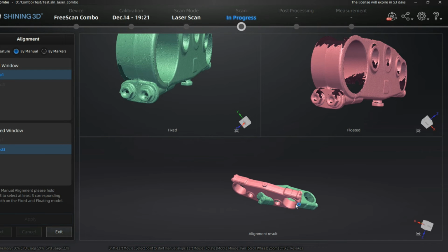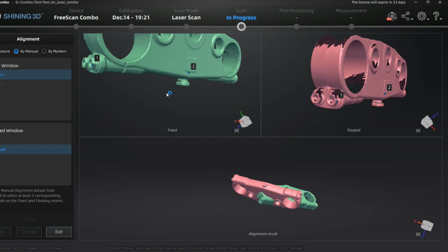Below the viewport, you can see the current situation of the alignment, and shift and left mouse is selecting areas. It's always positive if you pre-select orientation that is the same or similar on both sides. Why? It's much easier to find corresponding areas without screwing up your head.